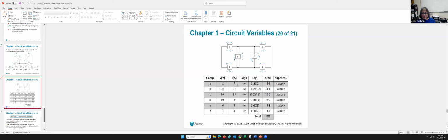So if you calculate, you have a voltage and a current on each one of these elements. They're given below, right? So in each case, you can compute. First of all, you can get the sign, you can get the amounts, calculate the power, whether it's positive or negative, and then the total is going to be 0. If there's an example in your textbook where the answer is not 0, it's because there's a flaw in the way that the problem was created. It's done on purpose because they want you to see how to use power as a check in a circuit.